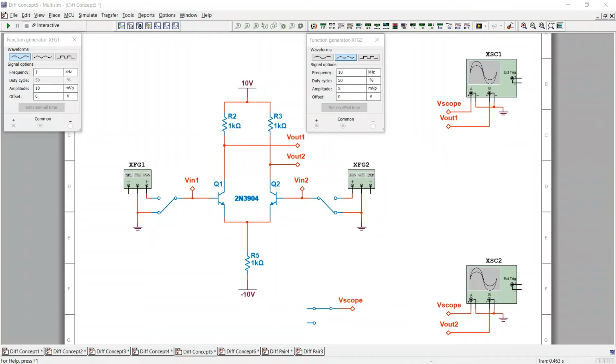So far, I've been showing you the differential amplifier using only one input, where I've been applying one input to Q1. What I'm going to do now is add a second signal generator, and apply that input to Q2. When we applied a signal into Q1, we found that the output off of the collector of Q1 was out of phase, but then we drove Q2 common base, and we got the output off of the other transistor, which was in phase. Put a signal in here: on the same collector, it's out of phase. On the other collector, it's in phase.